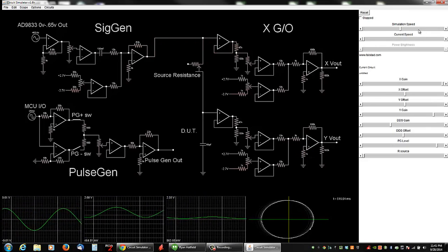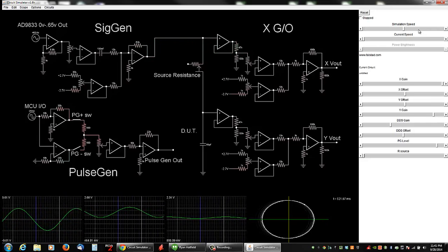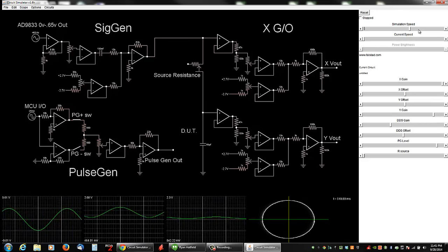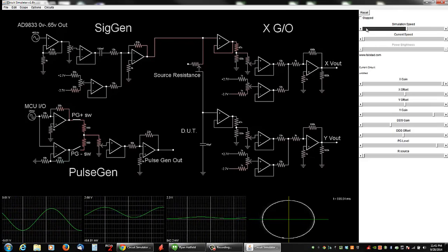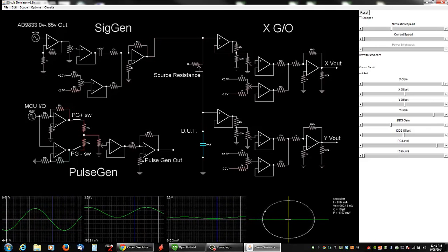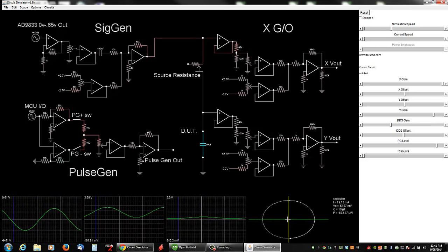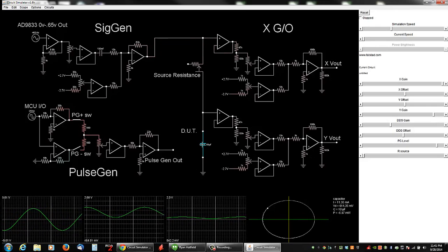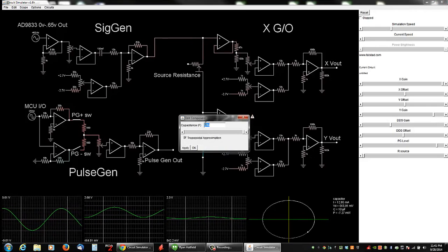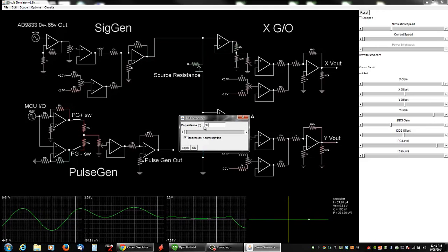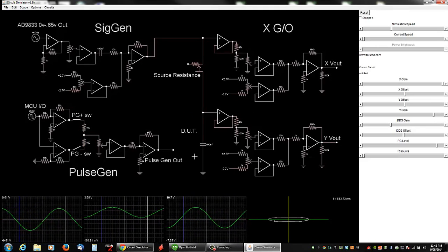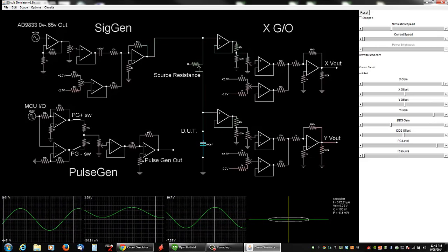You just speed it up here. It's going to get a little choppy, but it'll smooth out. That is what my scan will look like on the scope, or on my display anyways. A 10 microfarad capacitor will look like that. If I were to change that to, say, a 0.1 microfarad capacitor, and you see how it didn't rescale itself. So that's good. That's 0.1.